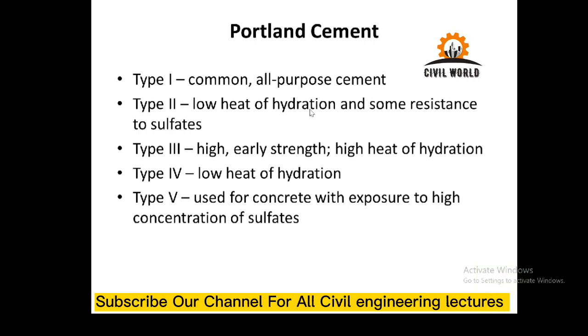They may be used in cold weather concreting, where sufficient early strength is required before the concrete is exposed to extreme weather, or in different types of structures where early removal of formwork is required and some additional construction weights need to be supported by the structure.